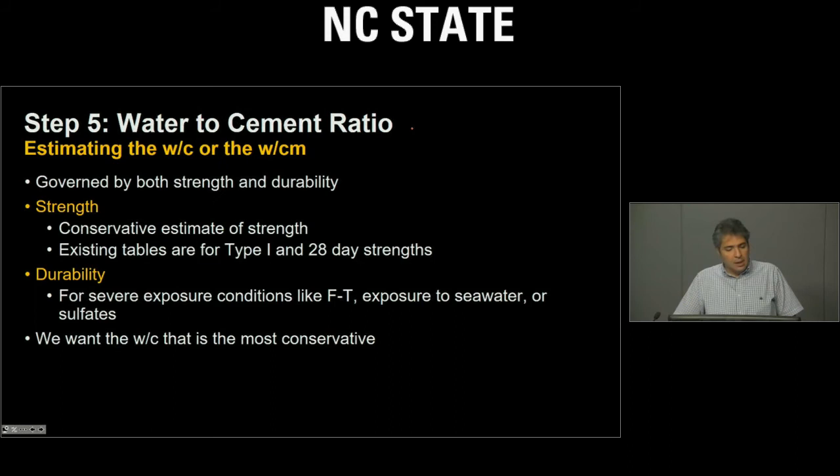Now, that we got a little bit of understanding why water to cementitious is important. And just to clarify over here, water to cementitious is, for example, if we have something like fly ash or silica fume inside our system, we basically use those as a cementitious material, and instead of cement, we divide the water by total mass of the cementitious material, and that is referred to as water to cementitious material, just to clarify that there is something in addition to cement inside the system.